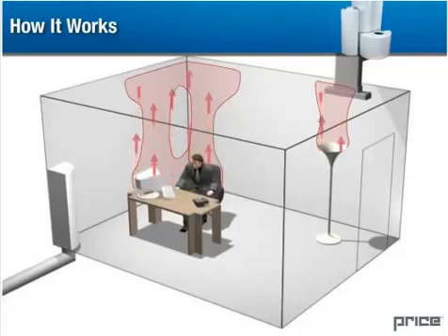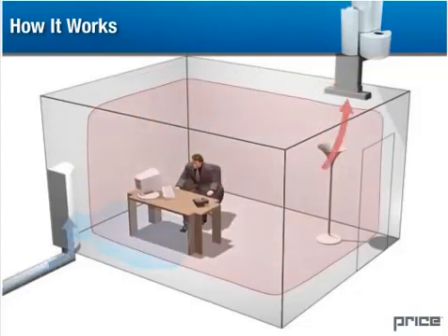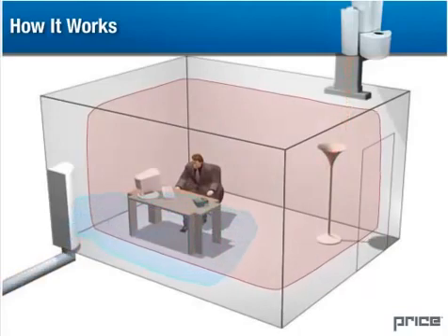The warm, contaminated air is lifted out of the breathing area, allowing clean air pooled near the floor to take its place. Depending on the power and geometry of these heat sources, the plumes could rise all the way to the ceiling. This means that the returns should be positioned where the highest temperatures occur, which in most cases is the upper part of the room.